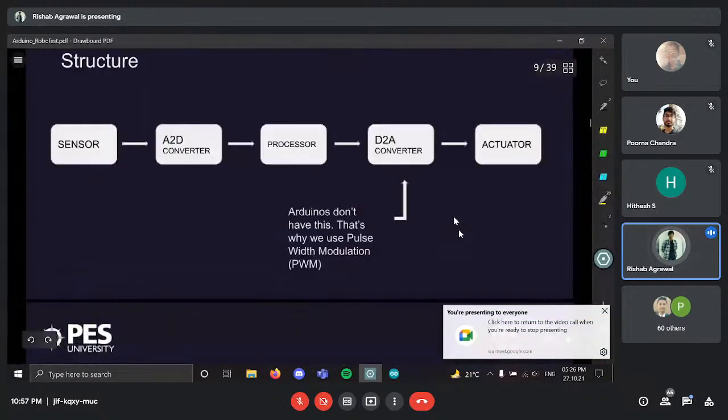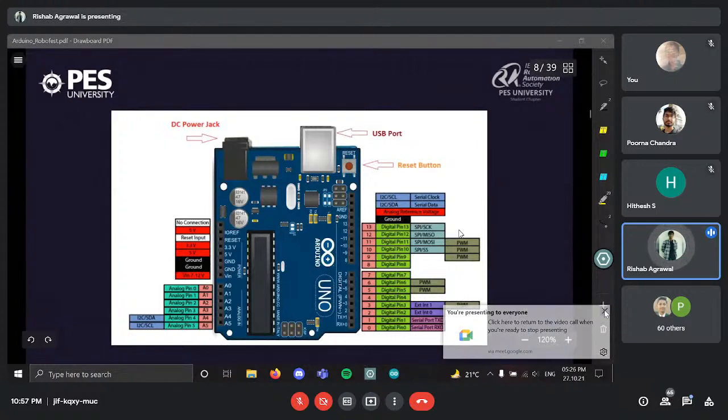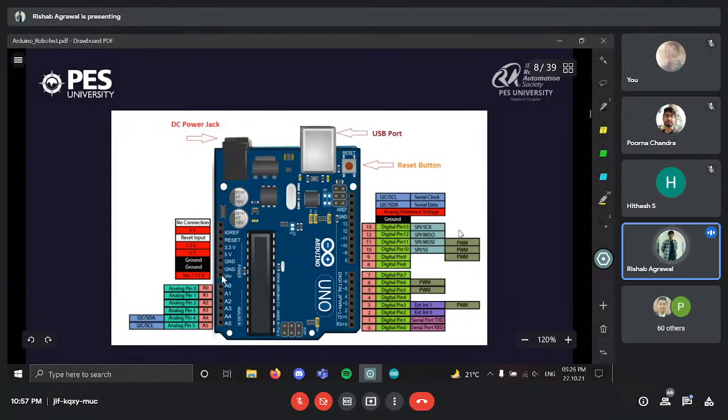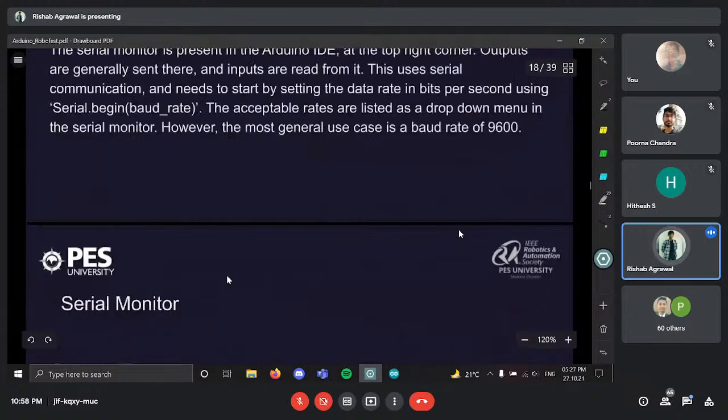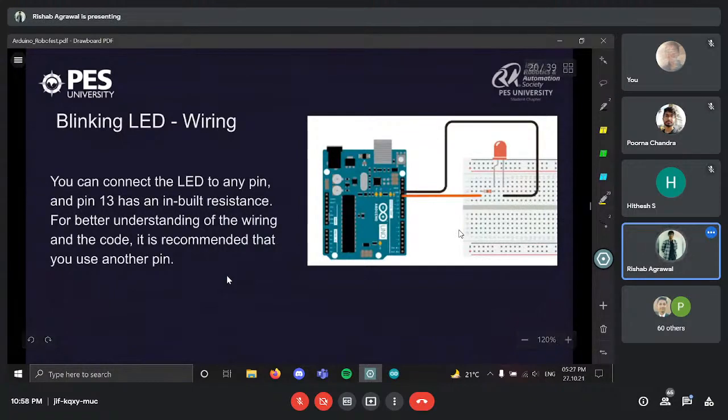In the Arduino Uno's pinout diagram, there is a V in and a ground option. So you can take an external battery and connect the positive wire to V in and the other to ground. That way the Arduino is powered using that. You can put the external battery on the chassis itself, and the car would run by itself after that. And for giving input, because you're using the serial monitor when connected to the laptop, we'll be looking into the Bluetooth module right now, so that you can give input using an app on your phone as well.